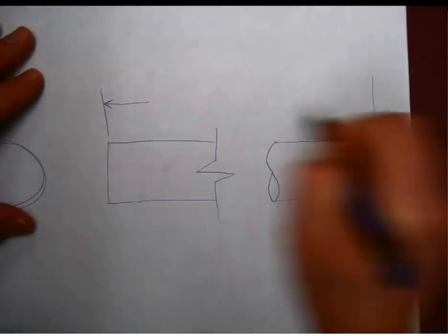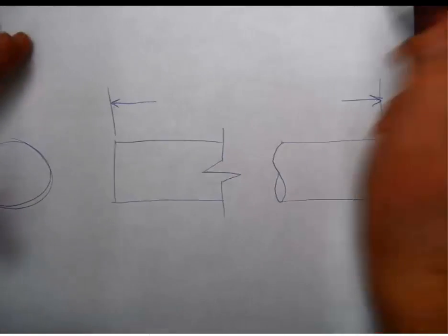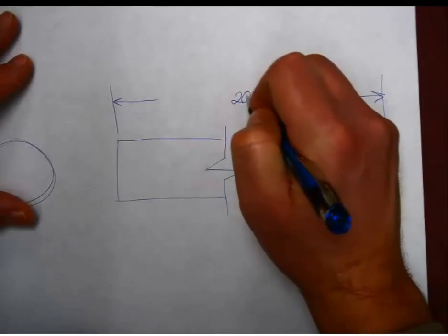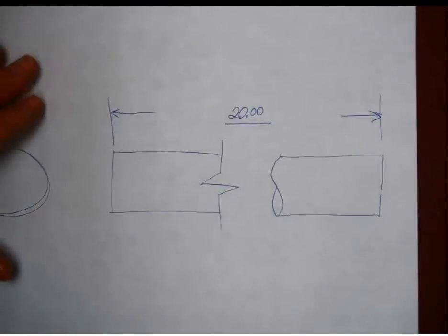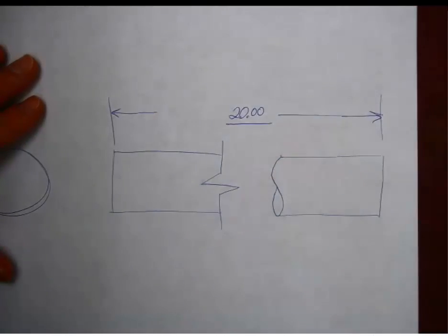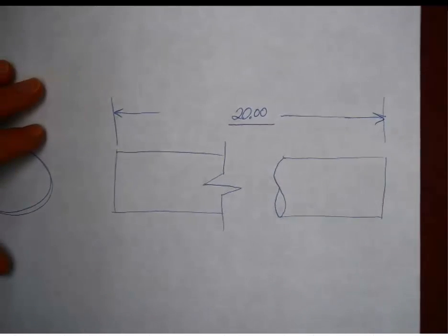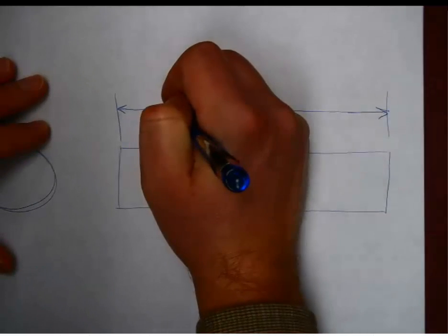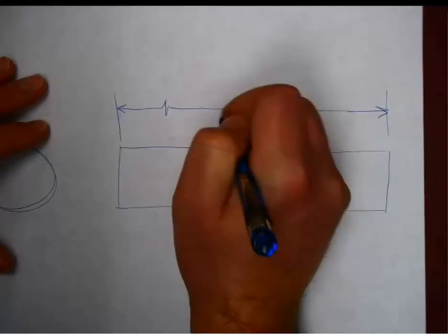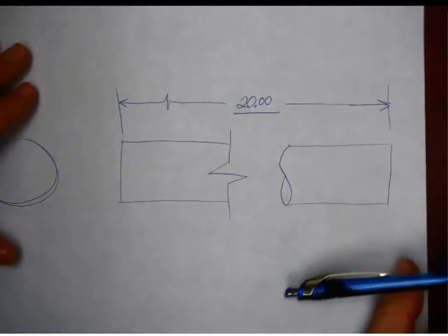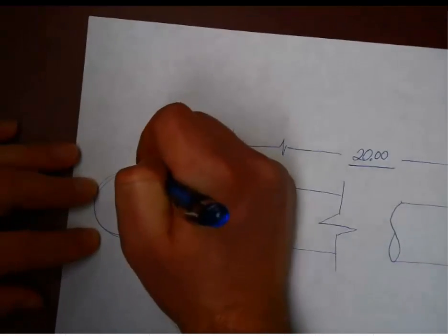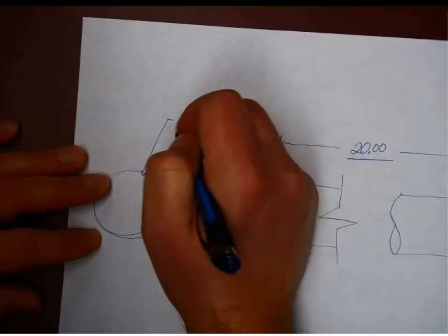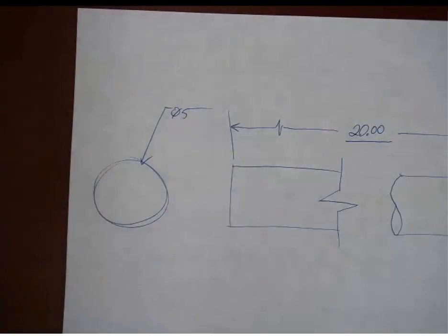the thing is it can't be measured on this piece of paper, right? So let's just say it was 20 inches. So what we'll do is we'll put a line underneath it to indicate that it's not to scale. And this is one of the only reasons why it makes sense to put a not to scale dimension in there. And then you'll often see a little symbol like that on the dimension line too, to call attention to the fact that it's a broken dimension. But if I dimensioned this, it was supposed to be a diameter 5, it's showing me 4.8, so I'm just going to edit the text and change it to diameter 5. Don't do that. That's bad.